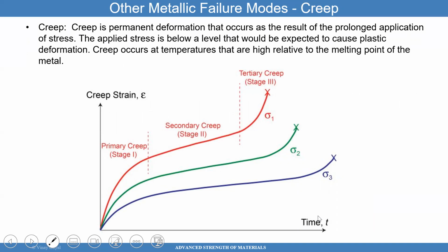The collapse was found to be due to creep, because there was a sustained loading condition on the cables that kept pulling the joints apart until, at a point in time, the joints just came flying apart. There's a video on YouTube that shows what occurred, and you can read the report to understand what creep is about.